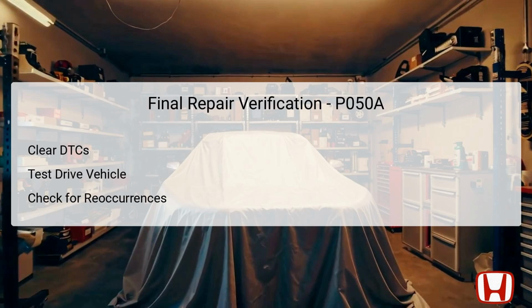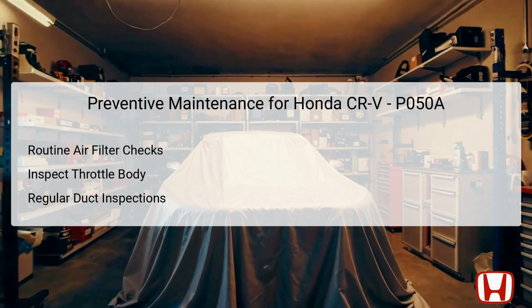If the DTC reoccurs, it would signal that the repairs may not have been effective, or other underlying issues might exist, necessitating further inspection and diagnostics. To prevent DTC P050A and ensure optimal engine performance, regular preventive maintenance is essential. Initiating a routine check on the air filter is critical, as a clean filter ensures adequate airflow to the engine, positively influencing the idle air control system.